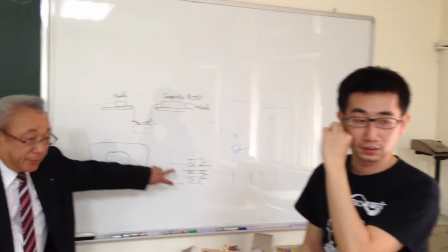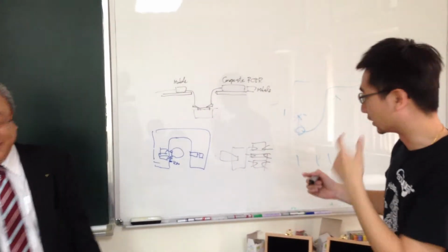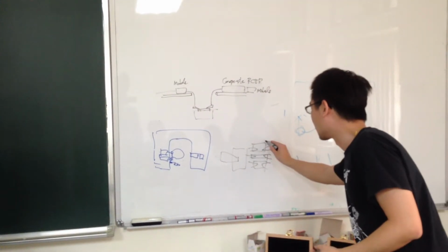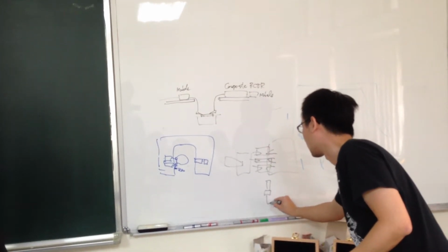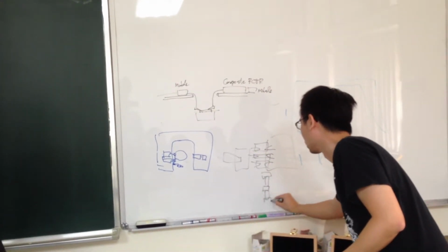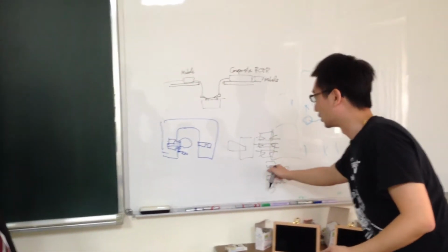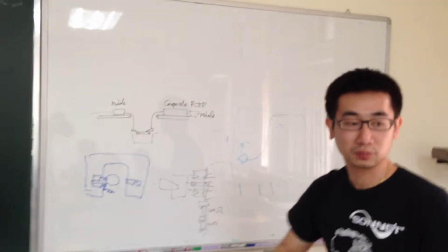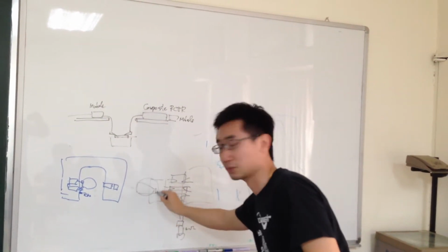For the noise calibration at the composite receiver. You mean making the termination on the wafer? No. Because the initial idea is using the receiver to contact a terminator on the substrate, right? And a 100 ohm resistance. Yes. Yeah, but when we want to create an input on wafer, we need another probe with a terminator.